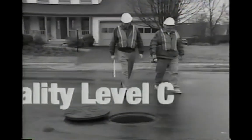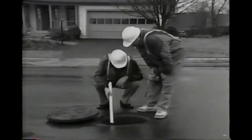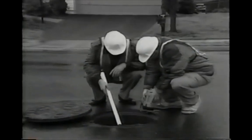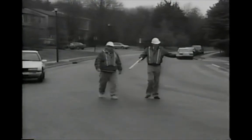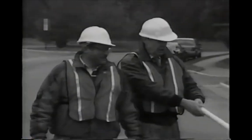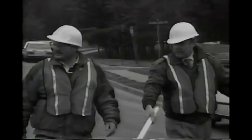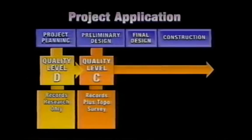Historically, quality level C was probably the most commonly used level of information for design purposes. It involves supplementing quality level D information with an above-ground survey of visible utility features, such as manholes or valve boxes. Looks like they've paved over the valves. But utility records and topside survey data are just not enough to provide an accurate picture of where subsurface utilities are located. Professional studies have shown a 15 to 30% error or omission rate with this approach. So quality level C should rarely be used for design purposes when underground utilities are present.